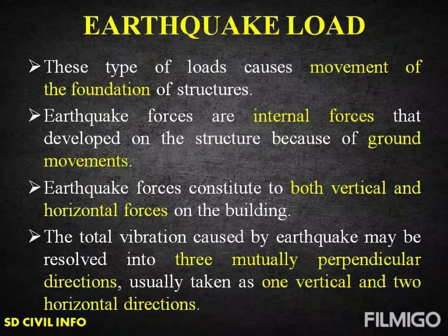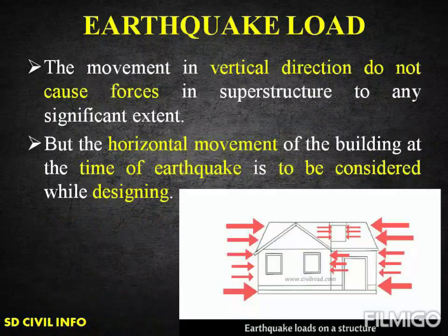These types of loads cause movement of the foundation of structures, and these forces are the internal forces that develop on the structure because of ground movement. These earthquake forces constitute both vertical and horizontal forces on the building, and the total vibration caused by the earthquake may be resolved into three mutually perpendicular directions, usually taken as one vertical and two horizontal directions.